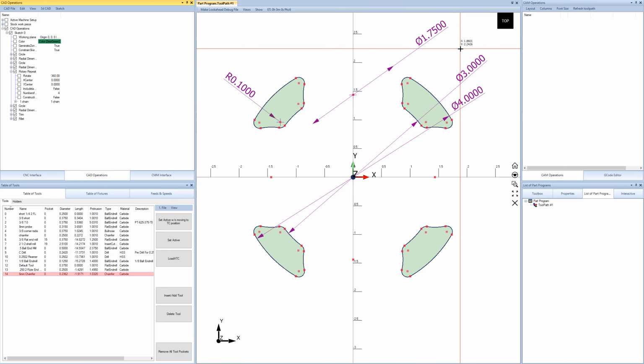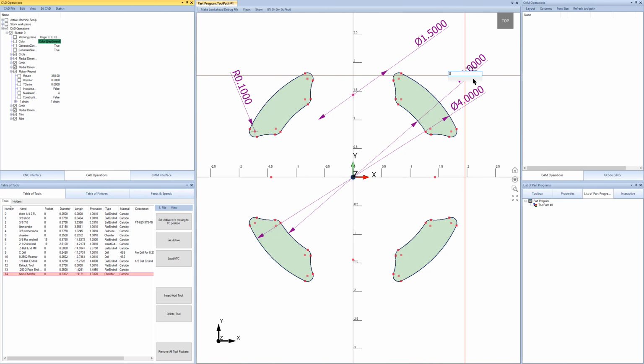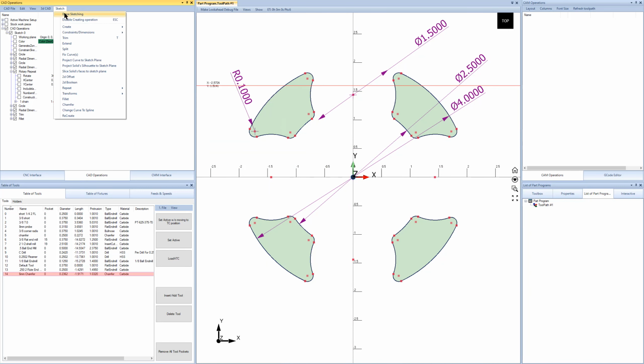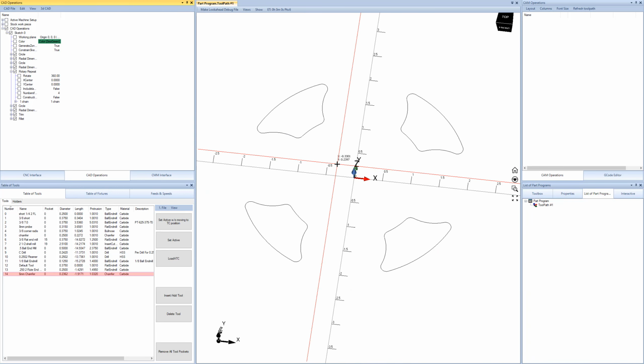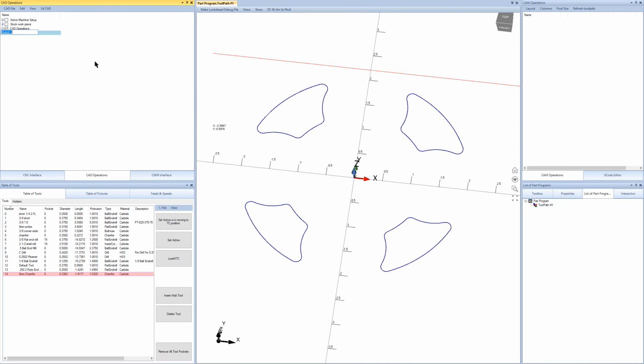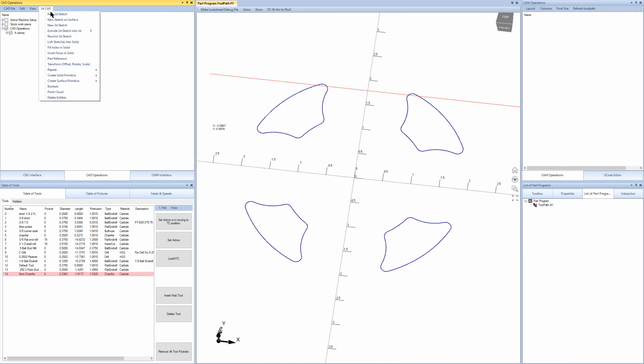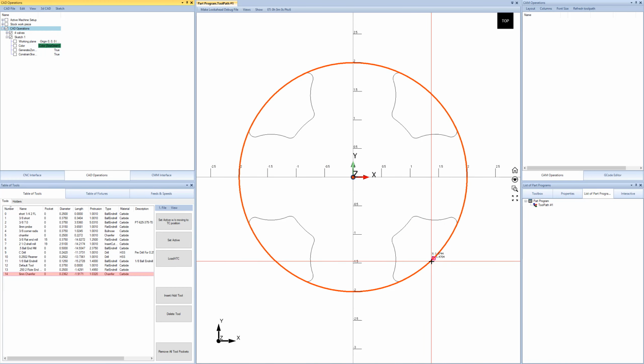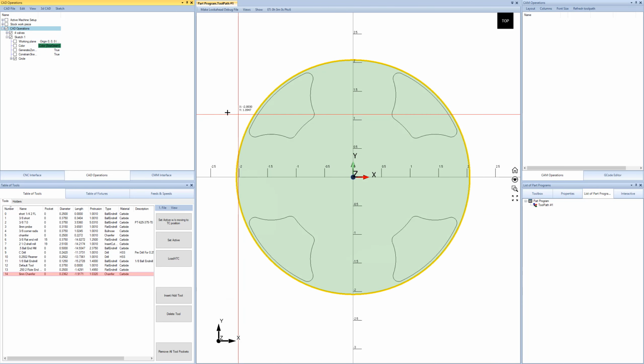That's mainly due to some of these new features that allow us to dimension things and keep things in relationship. This technology is called constraints. Okay, anyway, let's continue on here. I think we're pretty much done with this sketch, so we'll click Done Sketching. We're going to rename the sketch; we'll call this valve. I'm going to make another sketch and just create a simple circle in this one. Do something like that. Okay.